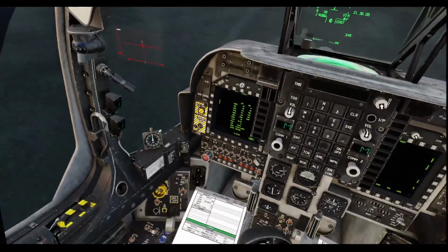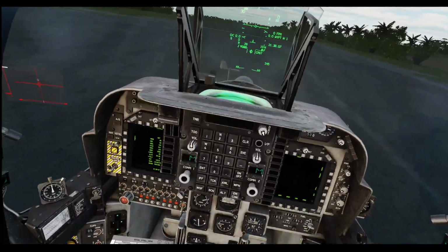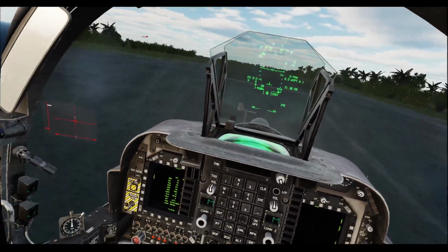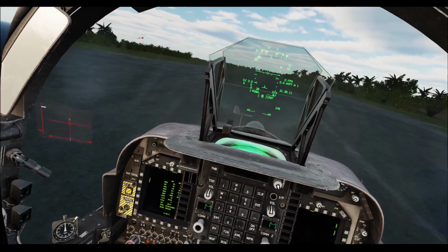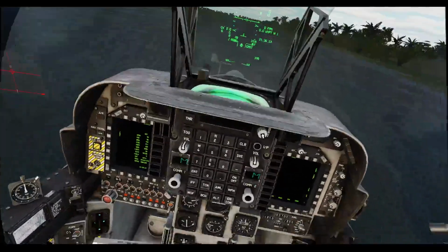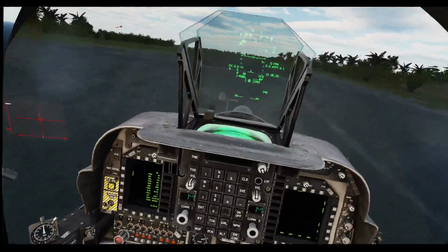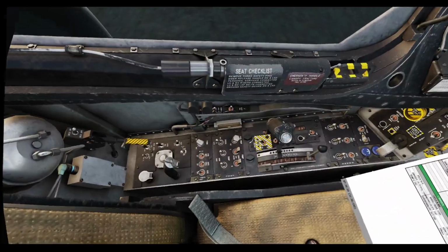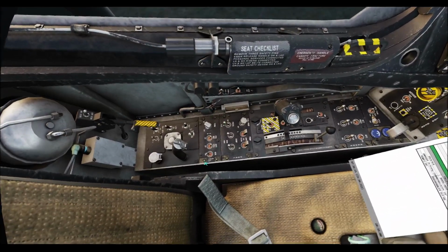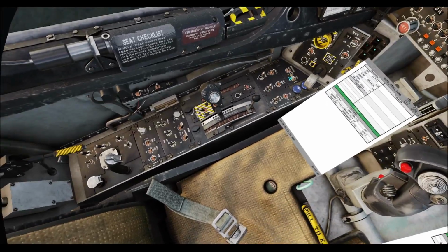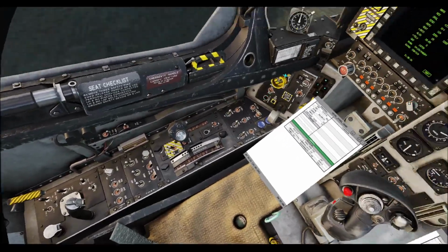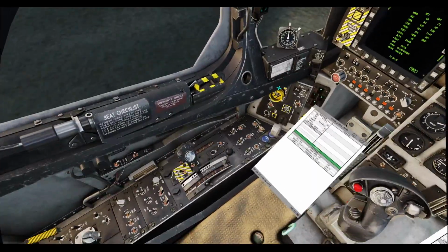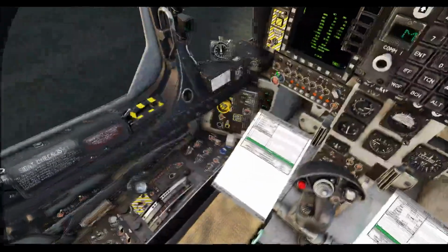However, if you then move into your one finger checks, which we will do now, you will find that your nozzle angle for the start of the takeoff is always the same, and in this case it's 10 degrees. Okay, so coming over the left, let's do the one finger checks. So we'll just make sure our lights are as desired. Coming forward, STO stop's already set, we've done that. Nozzles are at 10, we've set that.